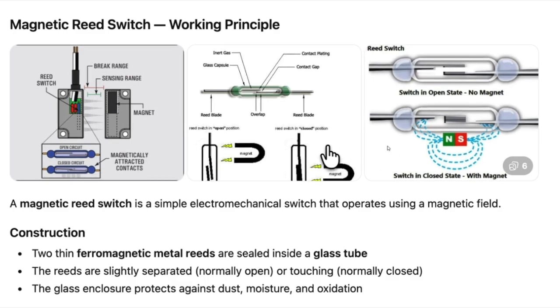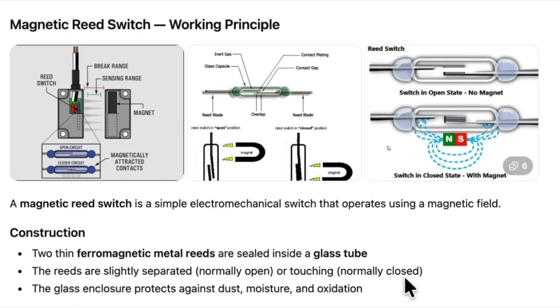I will show you an application of this, where we actually work with this. Let's say you have a limitation of cylindrical movement of any machine you have, right? Let's say you want to move it in the forward direction and then in the back direction, and you have set the limitation that at this position where the cylinder is going to stop, I need to receive this signal, and that signal you can use in your assembly level program. So this is the way it works, and it's simple, right?